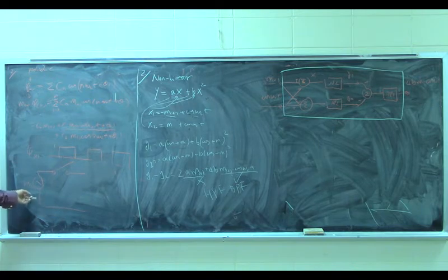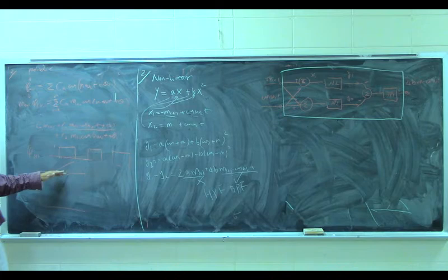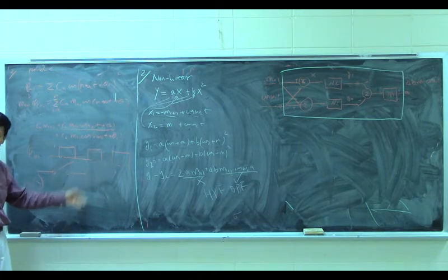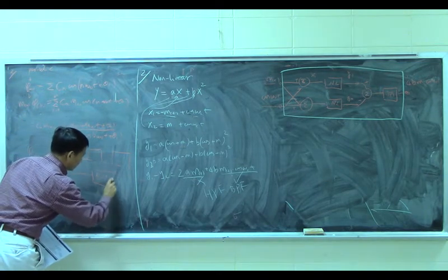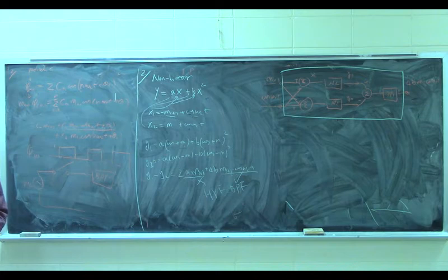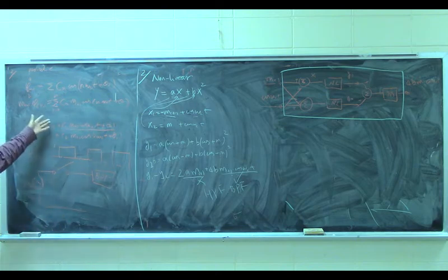You give me your baseband signal. I use a switch. I turn this on, off, on, off. Open, close, open, close. And then you need a band pass filter, and then you get the modulated signal. That's easy, right? So actually, we do not need any multiplier. I only need to use a switch.